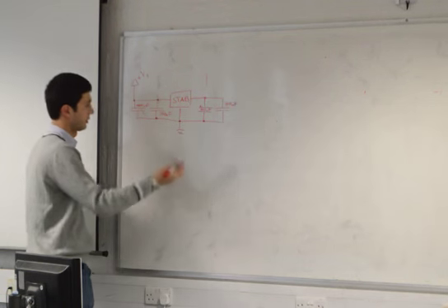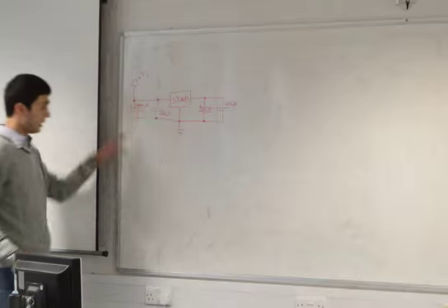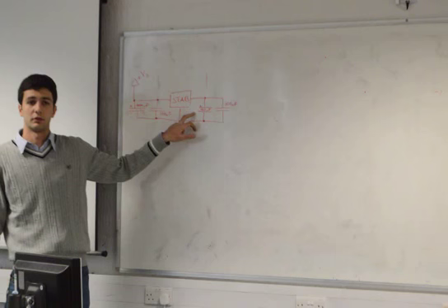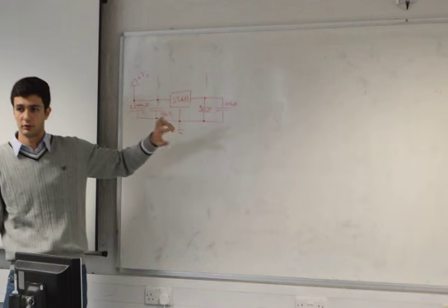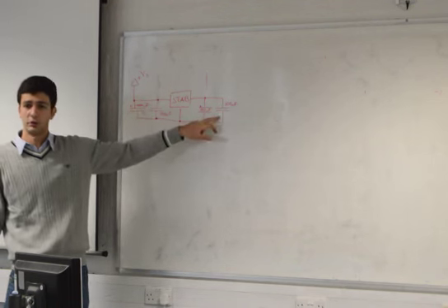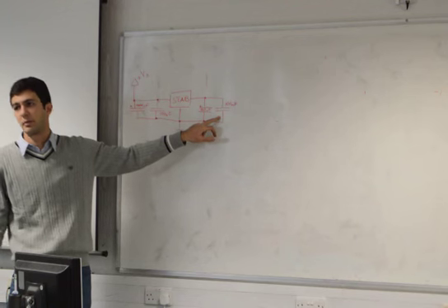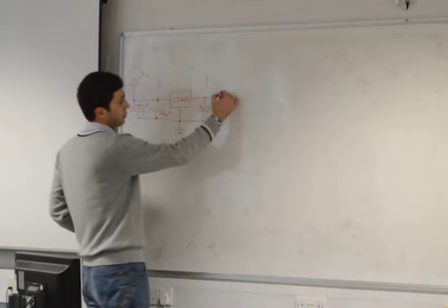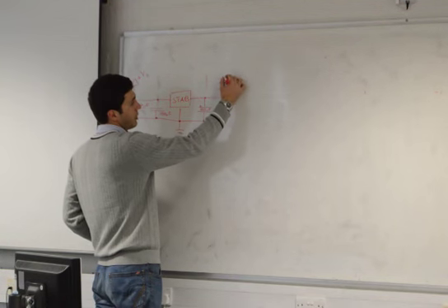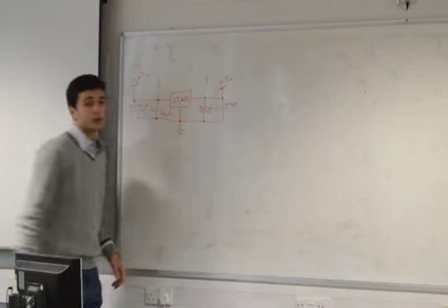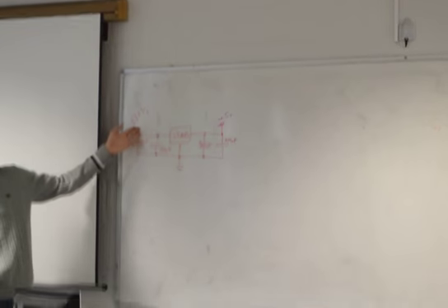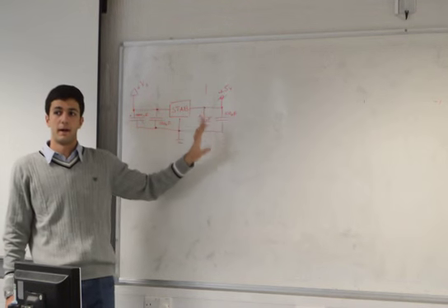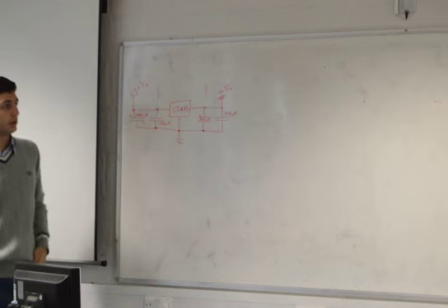Okay, so we have this part ready as well. The capacitors that I put a plus sign on are electrolytic. They have a polarity, you can't connect them the other way around. The ones without a plus sign are ceramic. And we have the point of plus 5 volts here, which is regulated. No matter how we change this voltage, we have a regular 5 volts output here. We're done with the supply voltage as well.